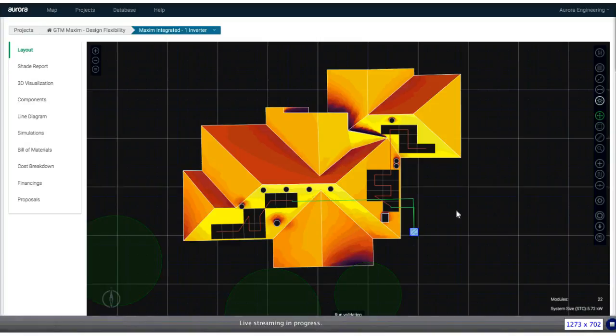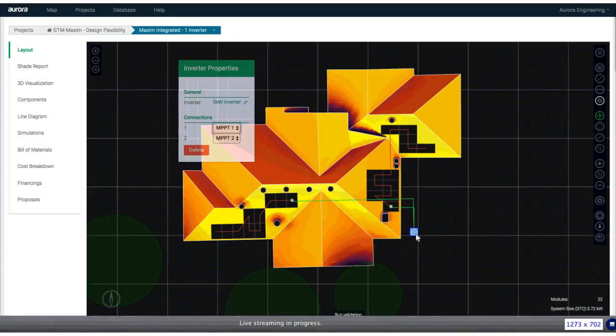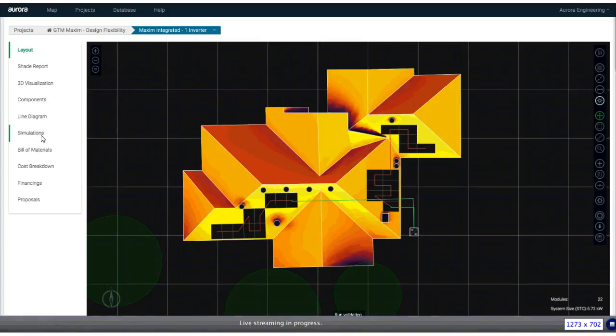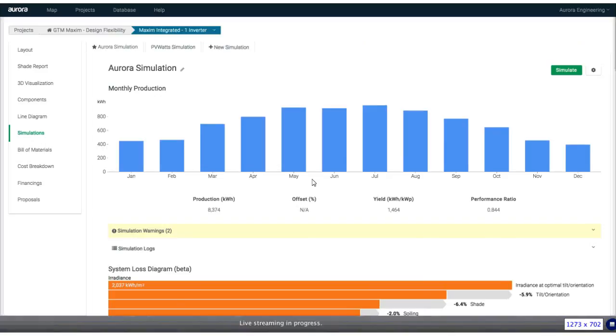But now our two groups of modules on the right side of the house, we have strung those together. And we're now able to do so because the cell string optimizers effectively isolate each cell string from every other cell string in that string of modules. And so if some are receiving less light, such as the ones facing east here, that's not going to impact the performance of those facing south that are producing more energy. So with these optimizers, we can now deal with this series mismatch and string across multiple roof planes.